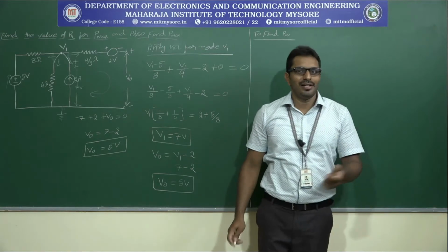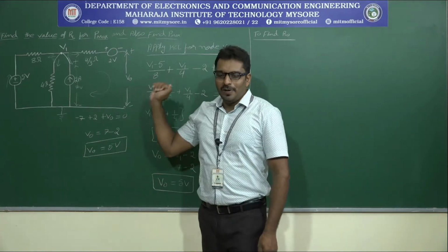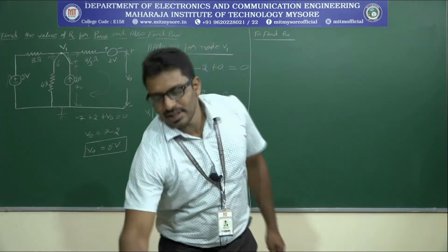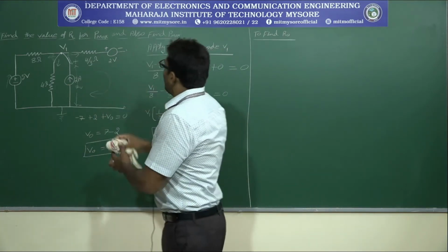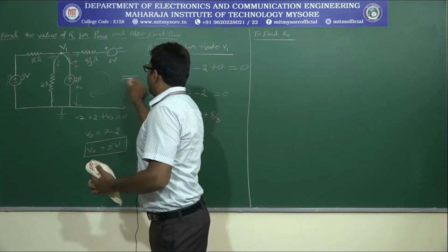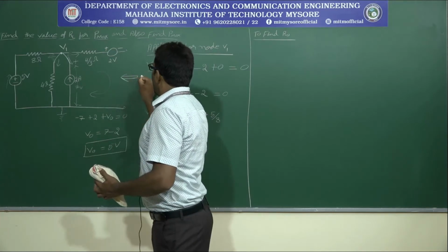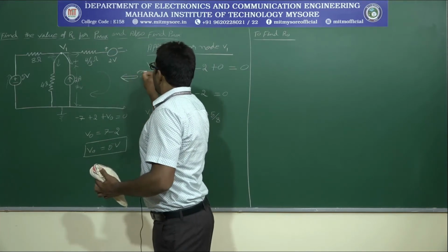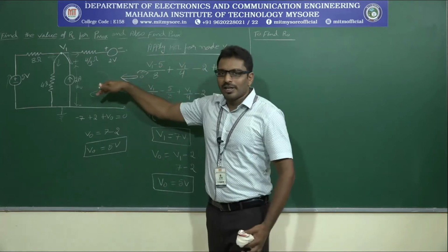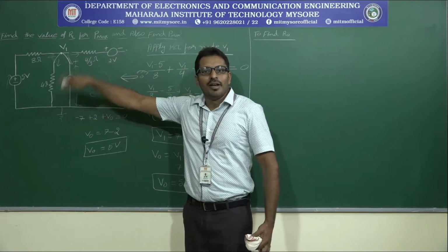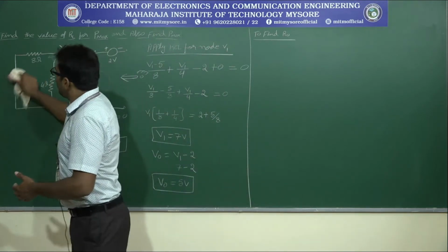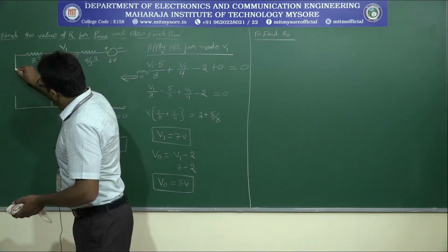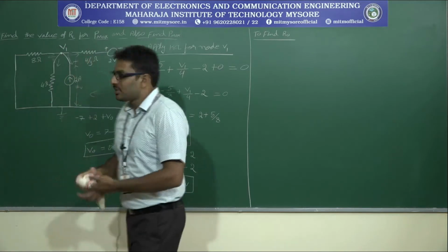To find out R naught, view from the load terminal into the circuit by replacing all voltage sources by short circuit.